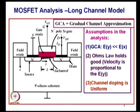Now, other assumptions in this analysis is channel doping is uniform. Okay. There are minor modifications on this if you have the non-uniform doping concentration, that I do not get down to discussion. I just took this up for continuity's sake. Okay. So, here this portion I have shown, that is where the channel is present. You can see that when you apply voltage to the gate, the p region gets inverted and becomes N type, so to say. Electrons are collected here, there is an inversion layer is present here.